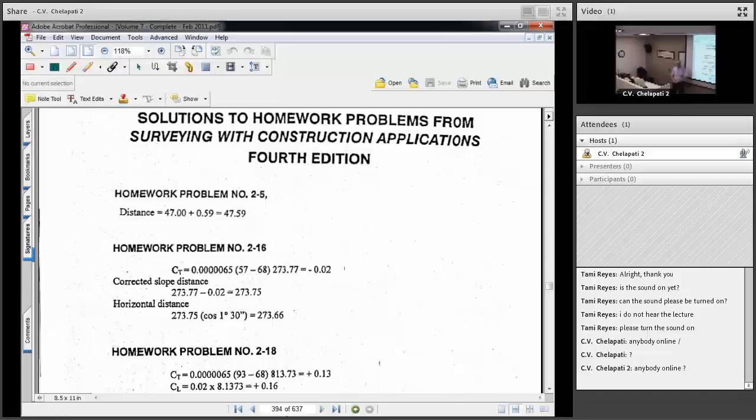So the head chainman reads the hundredths, and the rear chainman will read the foot part. Sometimes when you're measuring something and you have one person on each end, you say, okay, I think we're pretty close. But if it's something near a hundredth of a foot on my end, or near 99 hundredths on my end, you might hear the chainman say, give me a foot. What that means is you got to go to the next foot because it's not falling in that 1 foot that I have. Okay, you follow that?